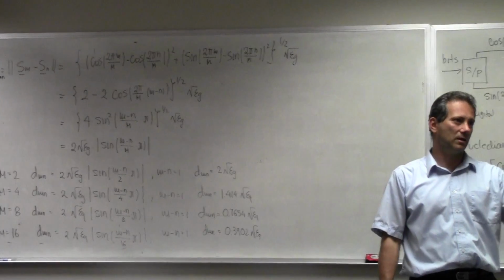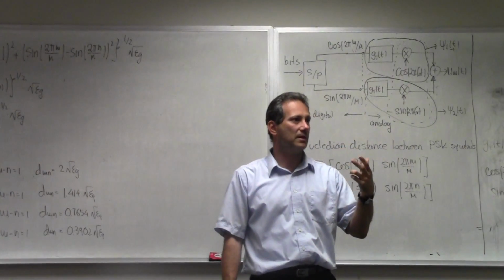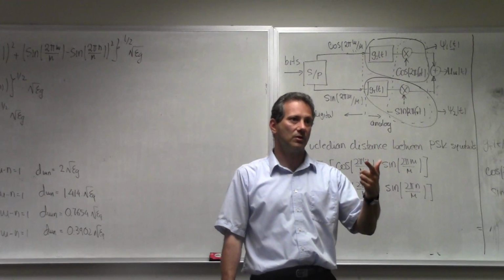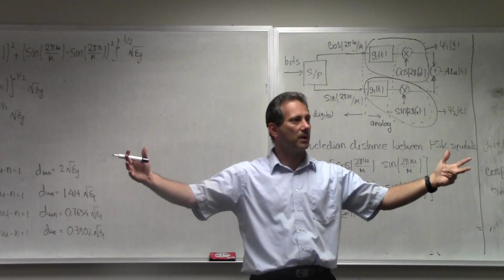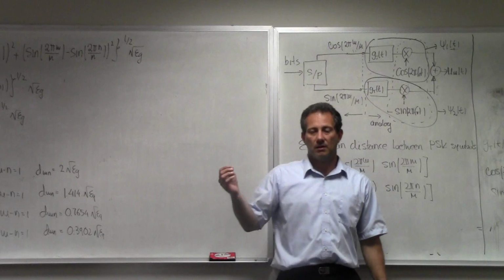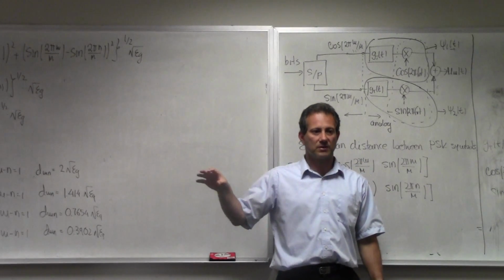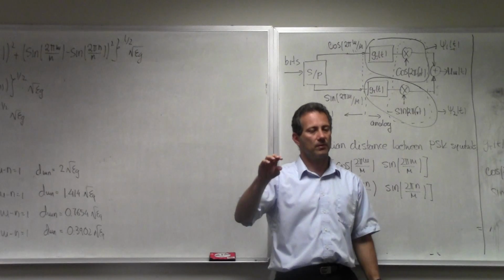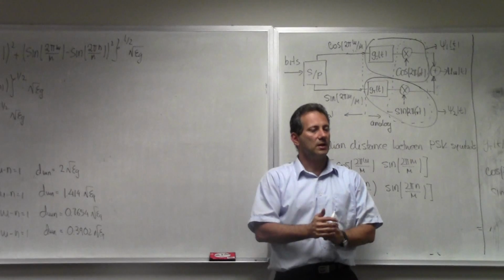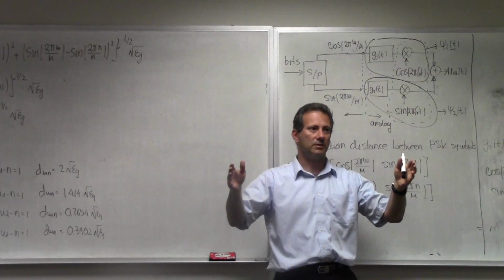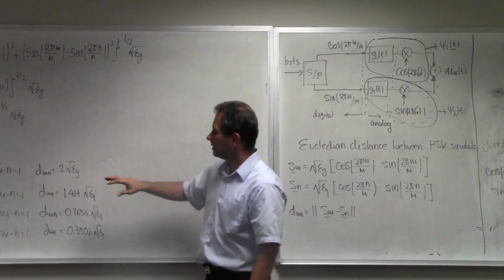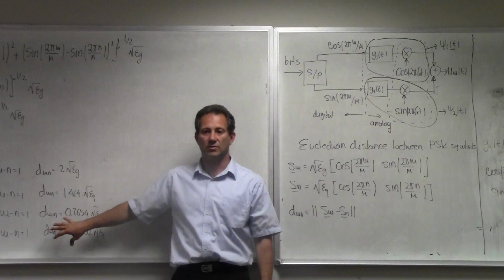One of the messages from there is that there's a fundamental trade-off between data rate, signal to noise ratio, and the occupied spectrum, the capacity, the bandwidth of your channel. Previously, we already know that the spectrum occupied by the digital signal is proportional to the symbol rate, or inversely proportional to 1 over T. So the same trade-off is kind of hidden in these equations here.